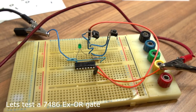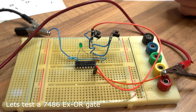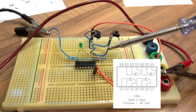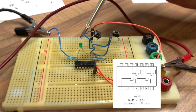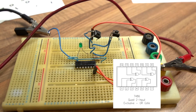Here's another chip. This one is a 2-input exclusive OR gate, and the chip number is a 7486. This has also got 4 gates in one package, 4 exclusive OR gates, each with 2 inputs. So I'm only using one of the package of 4 here for this test. And again, we've got our LED on the output, and we've got 2 switches here, just like before, on the 2 inputs A and B.